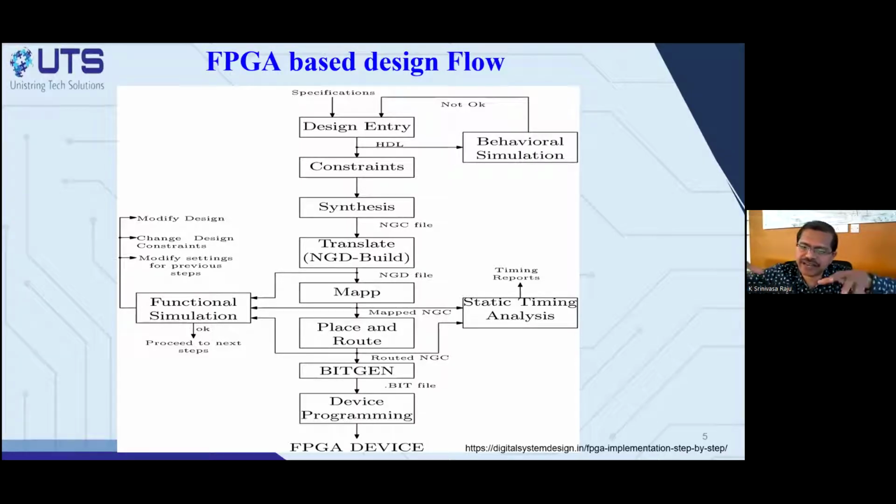Sure, sir. So then I have only pin constraints. Area constraints people rarely apply, but I have seen some advanced designs where 70-80% usage is envisaged, then people do also apply area constraints. Then there are some simple constraints most FPGA designers use. For example, the synthesis tool tries to optimize for area. It removes some of the design, thinking it is useless. The synthesis tool is not always intelligent enough to discover that. So people realize that depending on how you code, sometimes the synthesis tool will actually remove the logic. So we will add one constraint, a keep attribute kind of thing.